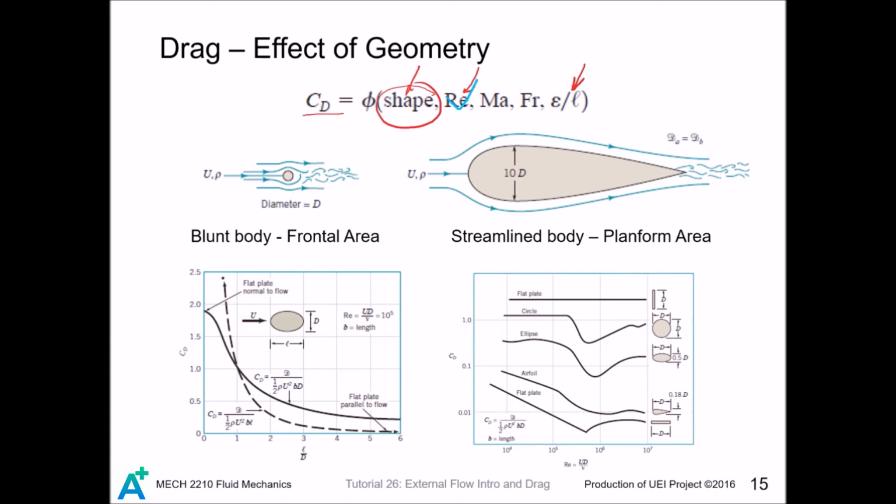And the size of the object is not really as important as the shape. In the figure here, can you believe that the drag produced by this guy is the same as the drag produced by this guy? But that is really the case. It is because the geometry of this guy blocks the flow. Shapes like sphere and cylinder are considered flow-blocking bodies, and we have another term, blunt bodies.